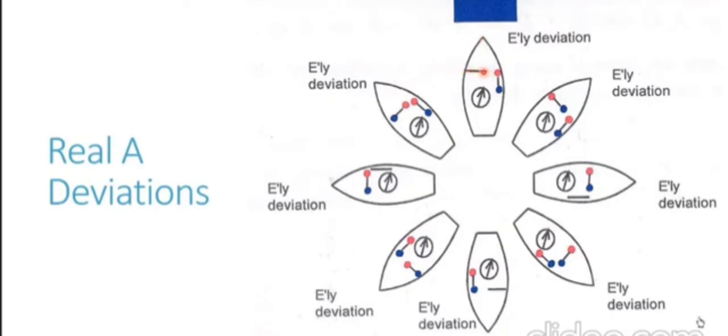So this beam is at right angles to the inducing field, or the magnetic field of the earth. Being at right angles, no induction happens. No magnetic field induction happens here, and the athwartship beam does not acquire any magnetism. There are no poles which are generated.